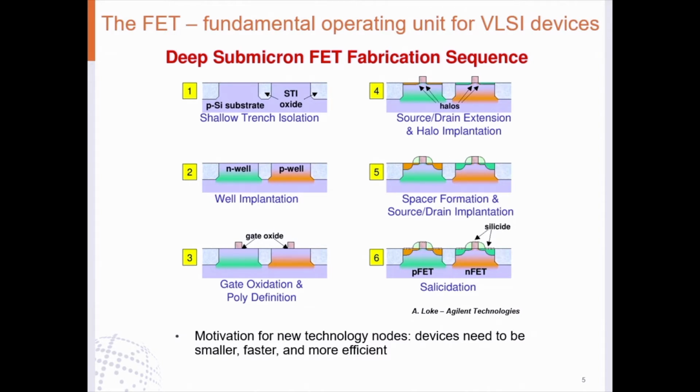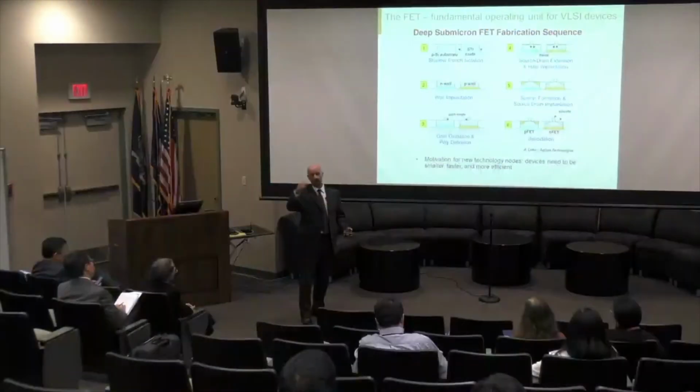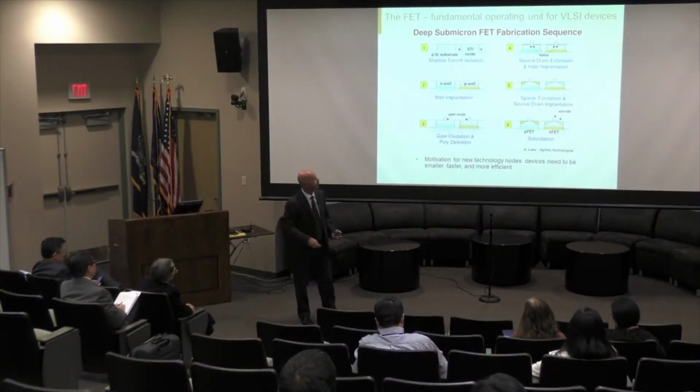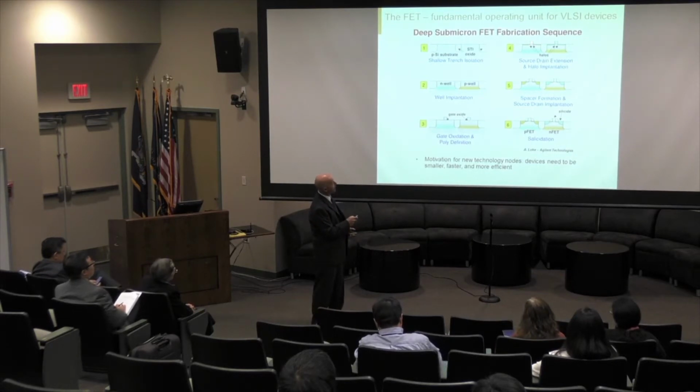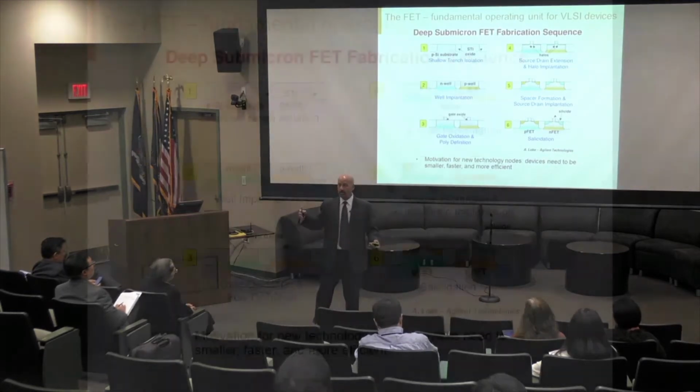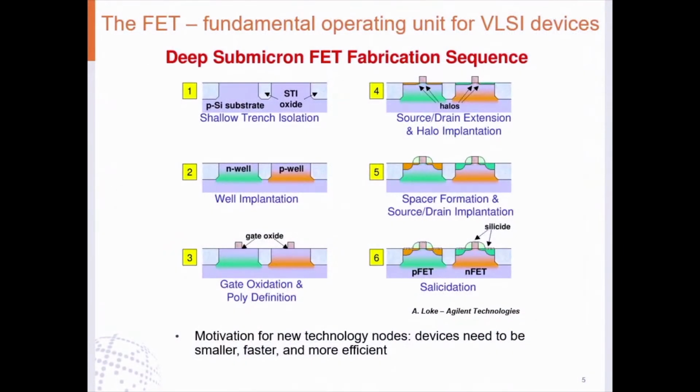And then oxidation step, we grow or we deposit a little polysilicon strip, which is where we're going to apply the charge, which is going to turn that device on or off. But these are some of the critical steps here. Okay, after we've got our polysilicon in place, the doping steps, where we actually do the final steps in forming that switch.